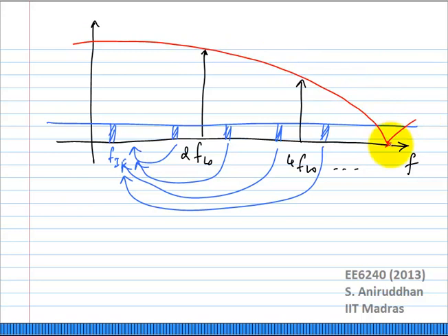What is this point? It's 1 over TS, right? It's FS, which is 1 over TS. So if you make this TS instant, the time for which it's sampled much smaller by increasing the device size, what happens is the amount of broadband noise which is folded down increases, but the actual noise floor itself will decrease.